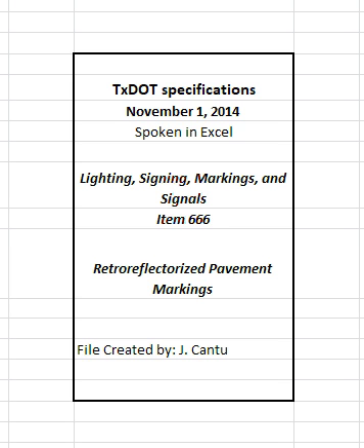4.3.1.1 Non-profile pavement markings. Apply Type 1 non-profile markings with a minimum thickness of 0.100 inches, 100 mils, for new markings and retracing water-based markings on surface treatments involving Item 316, Seal Coat, 0.060 inches, 60 mils, for retracing on thermoplastic pavement markings, or 0.090 inches, 90 mils, for all other Type 1 markings.